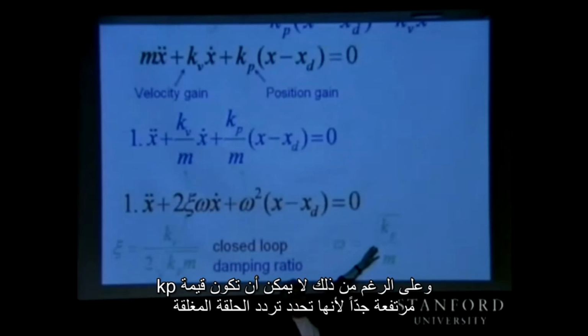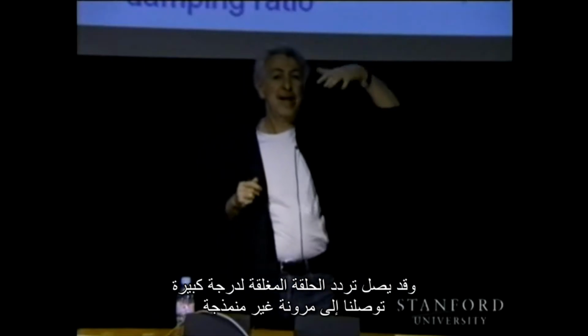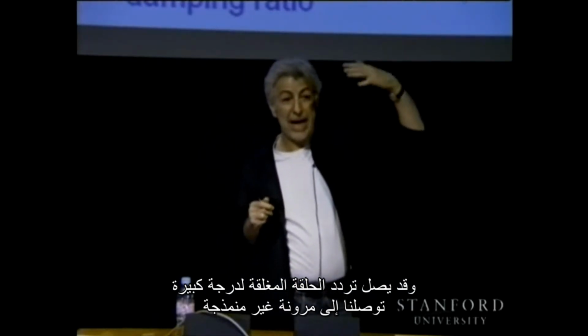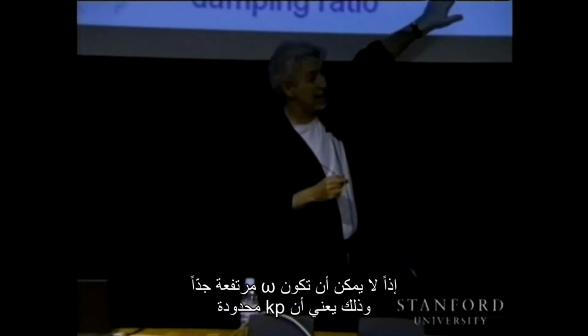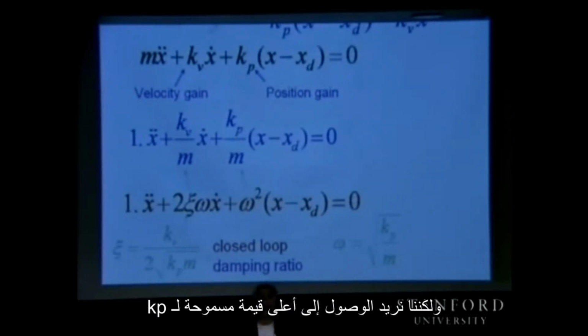However, KP cannot go too high because KP is deciding the closed loop frequency. And this closed loop frequency can go only as high as those unmodeled flexibilities. Actually, we cannot even come close to them. We have to stay away from them. So omega cannot be too high, which means KP has a limit. But we want to achieve the highest KP.